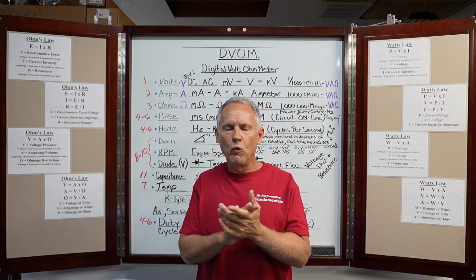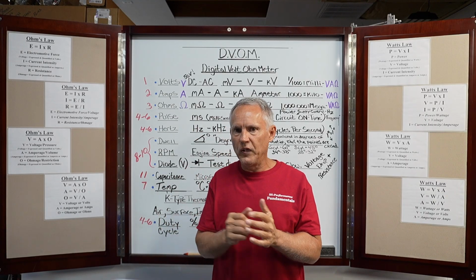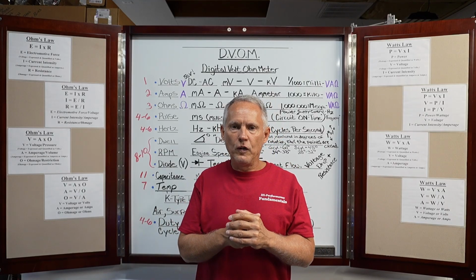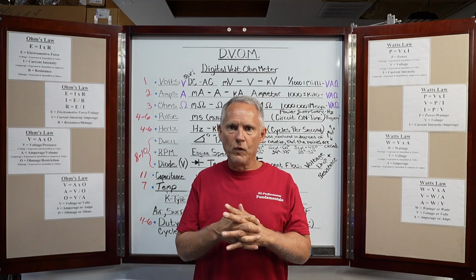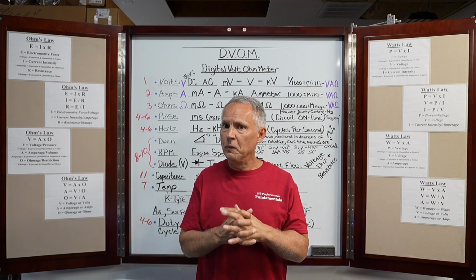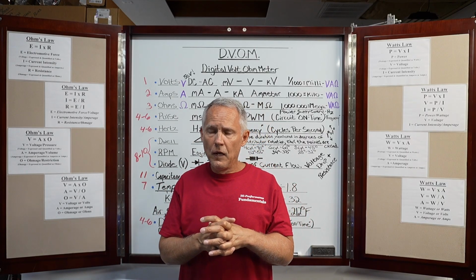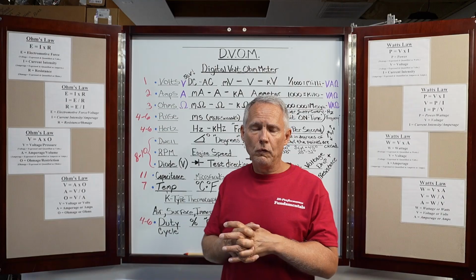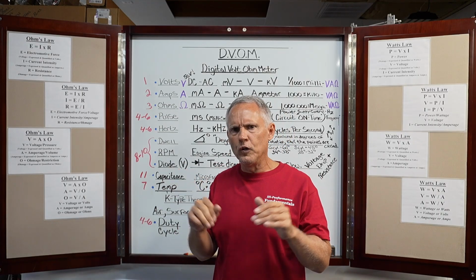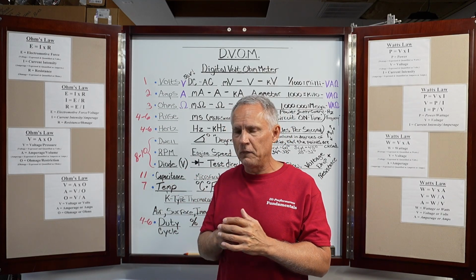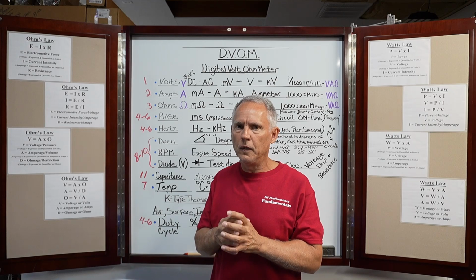If you're working on high voltage DC like that on electric vehicles, make sure that somebody's there. Never, ever, ever work alone. If something bad happens, nobody's going to be there to save you. If there is somebody there, make sure they understand that if you were electrocuted, it's not okay for you to say, oh, I'm good, I ain't worried about it, because 2 days from now you might be dead. You've got to get to the emergency room.